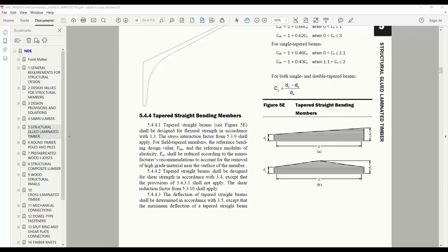Yeah, and I think a lot of manufacturers will give a similar answer. We've been using this product. It has worked for us. It might be something different than what your organization uses, but there's a lot of adhesives out there that comply with the relevant standards. Generally, in all the engineered wood products, you're going to find adhesives that are resistant to fire. I know many years ago there were some issues with adhesives and finger jointed studs, but those adhesives aren't being used with engineered lumber products. The structural products, I don't think that's a concern.